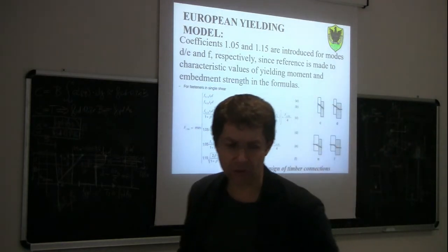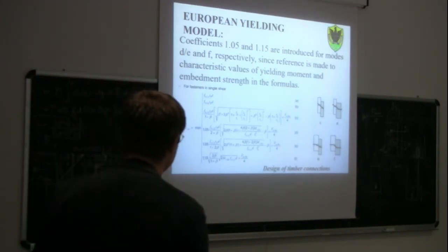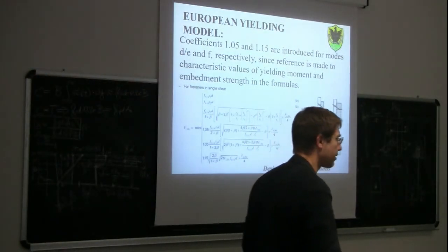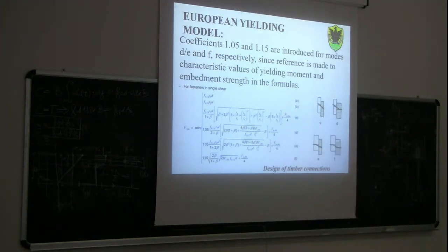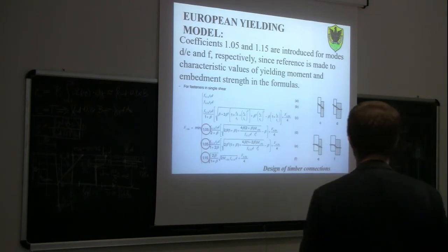What is the rope effect? The rope effect takes into consideration an important effect related to the fact that in some fasteners there is also a withdrawal strength. So the fasteners have some resistance to extraction, resistenza all'estrazione, and as such, when we load the specimen, we can get some support from friction. You can see it better with this figure here.